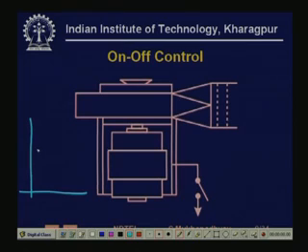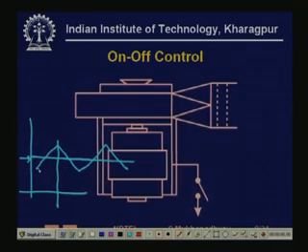So you see, if you switch on the fan, the flow rate will rise for a little time, then it will fall again, and then you will switch it on and then switch it off. So you will be able to establish an average flow, and this average will actually depend on what is known as the duty ratio. So this is on, this is off. Or rather, what will happen is that it will not rise slowly because the time constant will be fast enough, rather it will be like this.